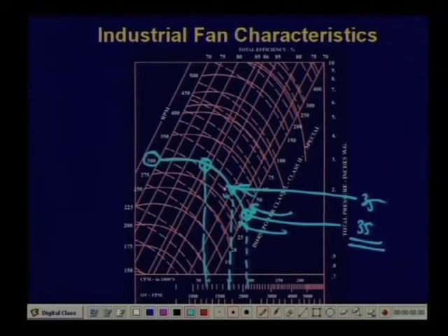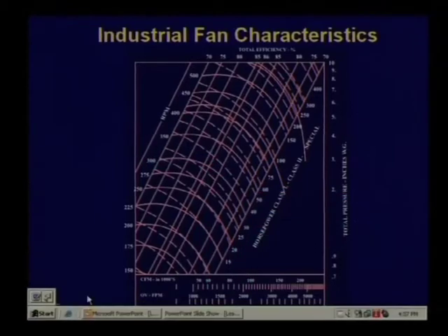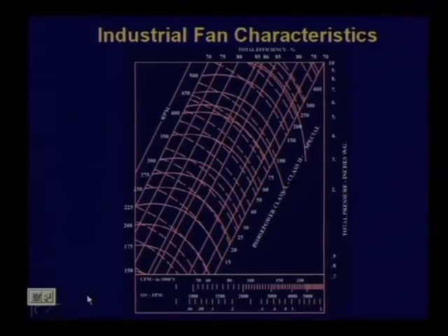You see, this is the 30 curve, this is the 40 curve. It is actually a nonlinear variation, because from 50 to 60, 60 to 70 it is gradually getting closer. So this is something like 31, 32, it is slightly reduced. This is how you get those figures from an actual pump characteristic.